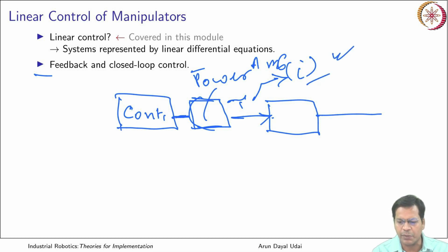So this current is basically decided by the controller output, and this is nothing but a power amplifier, because you know this signal is not good enough to directly drive the motors which are there in your robot, which is here. So you have your robot which goes here. This is driven by the huge amount of current which is here, but this is nothing but the signal that comes out of the controller. So now what goes to the controller?